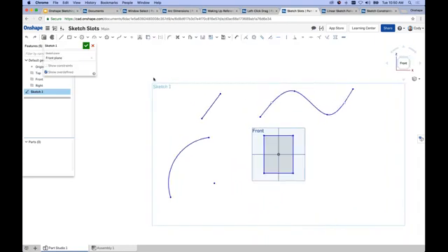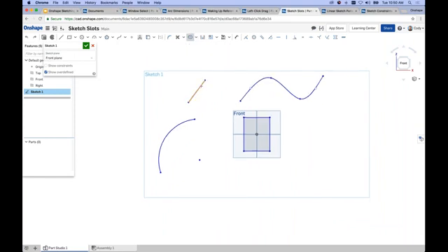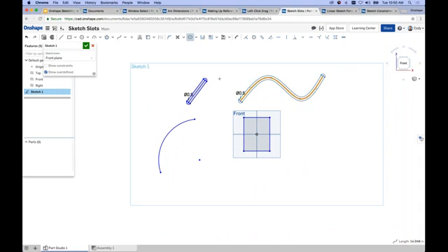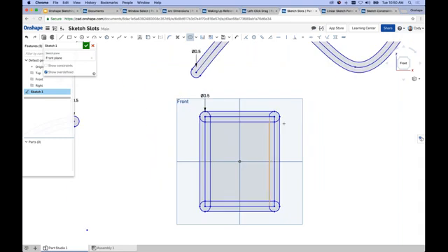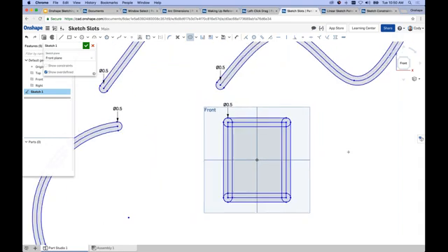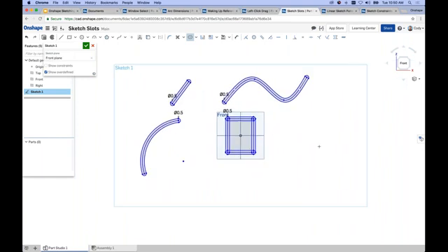So just to illustrate, this takes just a moment, but under the offset feature in the sketch toolbar, you have slot. And again, of course, it works for your typical straight line slots, but it also works for splines, right? Or arcs, right? Or rectangles. So if you're just looking for a fast way to generate slots around geometry, this is a tool that will work for you. And it's not just for straight lines, right? So I guess that's my big tip.